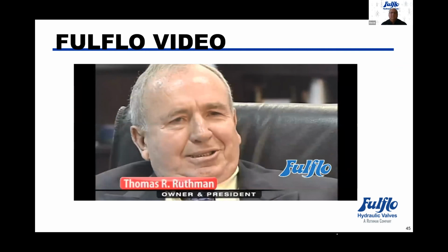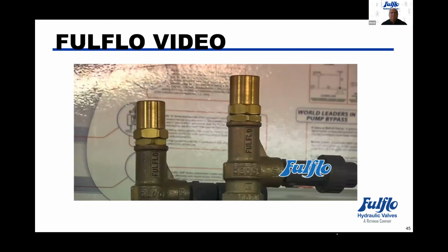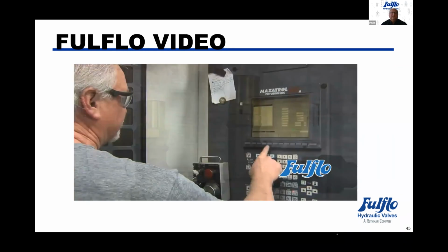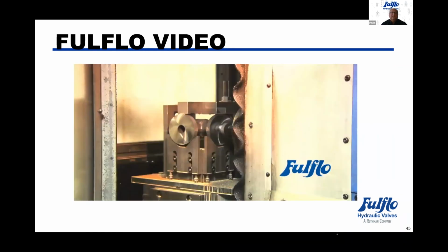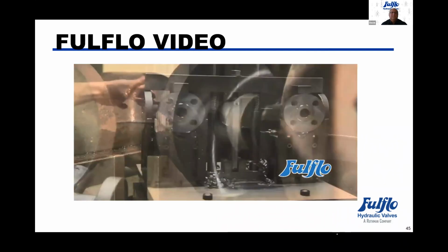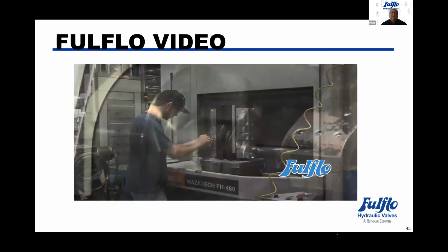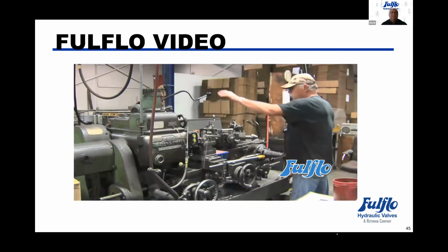An essential part of the world's manufacturing process today, Fulflo hydraulic relief valves operate effectively with all types of liquid in a full range of viscosities. The Fulflo valve is for liquid service only, no air, gas, or steam. It is used for continuous duty, pressure regulation, back pressure control, pump bypass relief, elimination of pump deadhead, and pump system balance, all with a chatter-free performance. One valve can do it all.